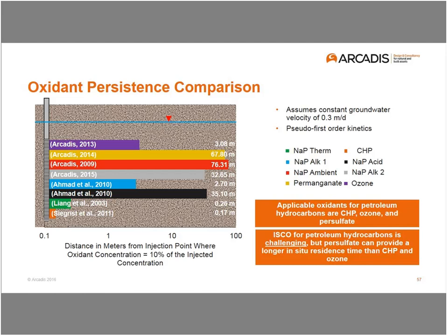COCs. Analyzing this a little bit more, we note that ozone, which has solubility and mass transfer limitations associated with it, is soluble to about 6% by volume, and the dissolution of the air bubbles into the liquid can have an efficiency that's typically less than 5%. It's still likely to influence a reasonable ROI, which is about 10 feet or 3 meters. Catalyzed hydrogen peroxide,